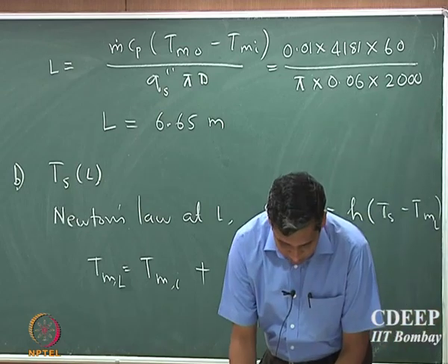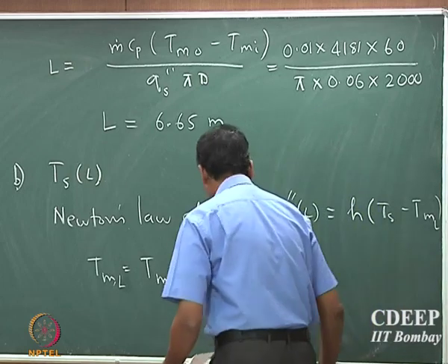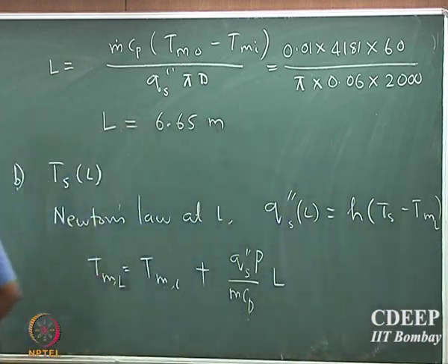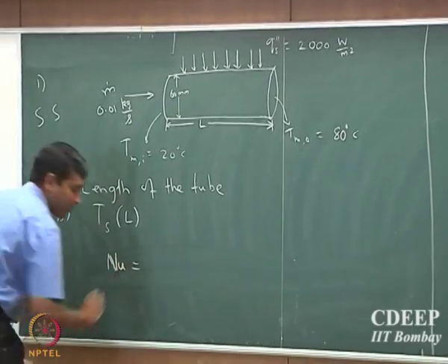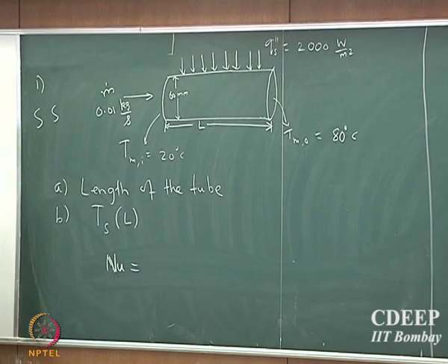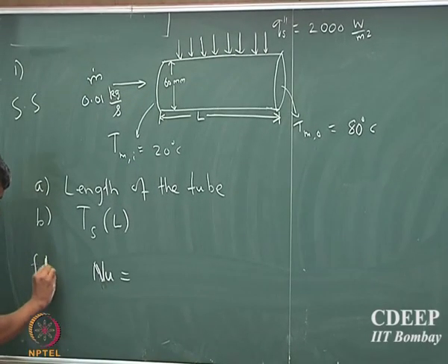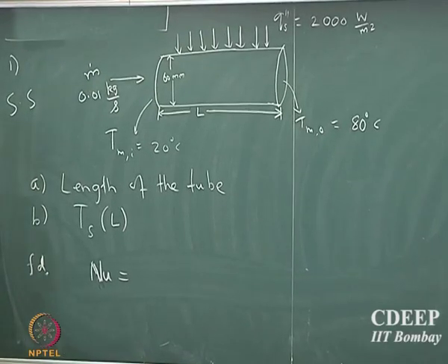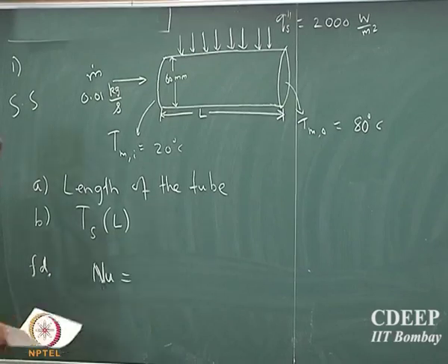So we can use this information, and we can also find, I have not given other numbers here, what the Nusselt number is. What's the Nusselt number for the constant flux case? If I assume that it's fully developed, it's a constant, and it's 4.36.